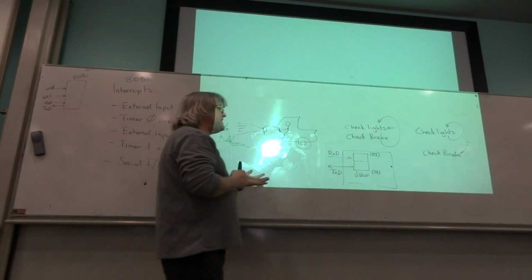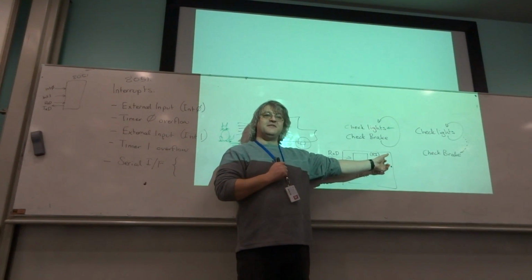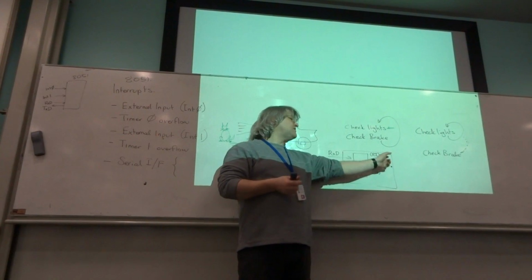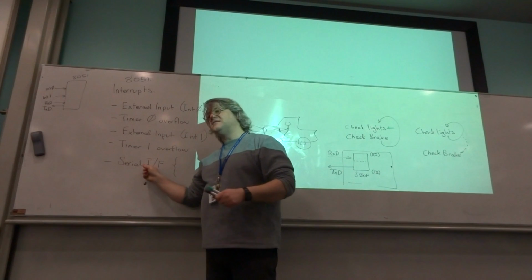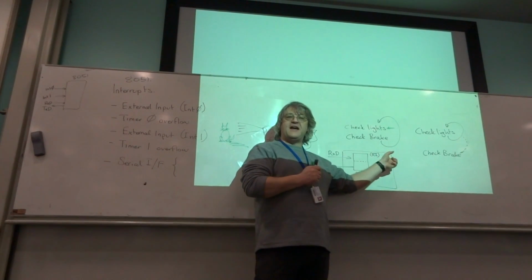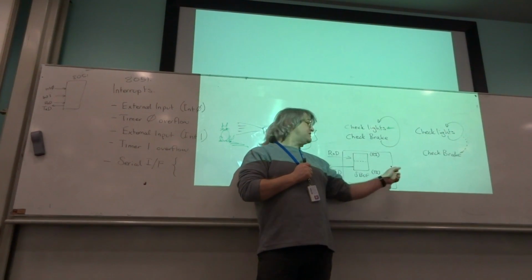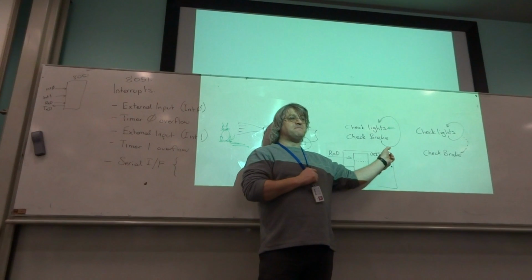So if a serial interface interrupt happens, you're not quite sure what's happened. Is it because you've sent something out and it's finished, or is it because something's arrived? So you would have to interrogate these flags to find out what was the cause of the interrupt. Is it because I've finished transmission, or because something fresh has arrived and I need to read it?